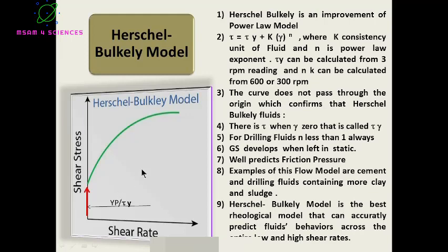The curve does not pass through the origin. That means there will be a yield point, and fluids here tend to develop gel strength if the fluid is in static condition. There will be a reading for shear stress even if the shear rate is 0.